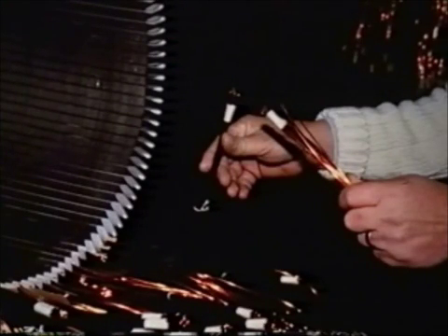Each coil has a start and finish wire. These wires are used to connect 2 or more coils in pairs or groups. The connecting coils are then either connected in series or parallel. Series connection is tying the finish lead of one coil to the start of another coil.